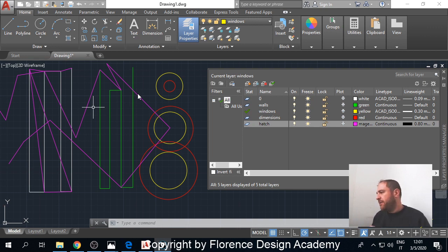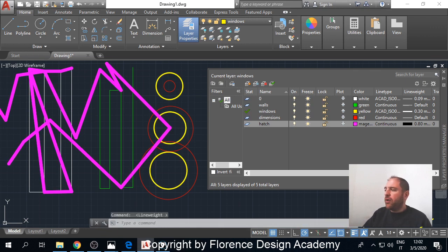Then see the magic, because if I have changed line weight in my layers and I want to check that layers have different line weight, I can simply click this option with the left button, and this will be turned on, and when it is turned on it is blue. But now I can see that my purple layer, that I have just randomly selected to be 0.8, is showing me a pretty thick visible line weight.